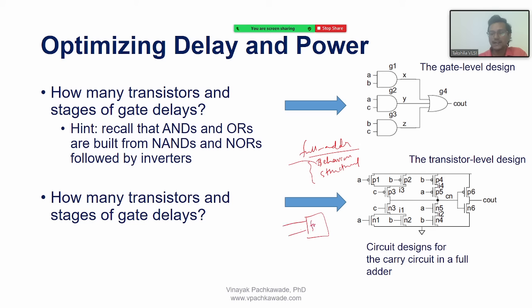It tells the tool, okay, implement me or give me a circuit and behavior of the full adder. So I have A, B and C inputs and outputs, and the synthesis tool will take care of it. It will just take the IPs from the libraries and implement this logic on its own, because I have just described the behavior as a logic designer.